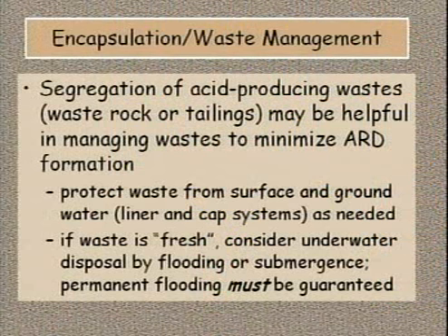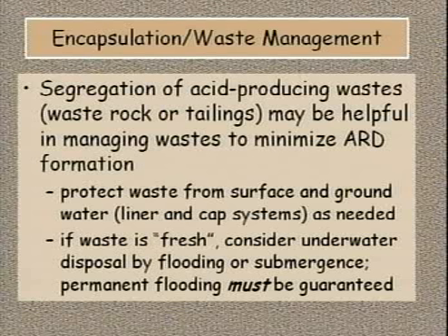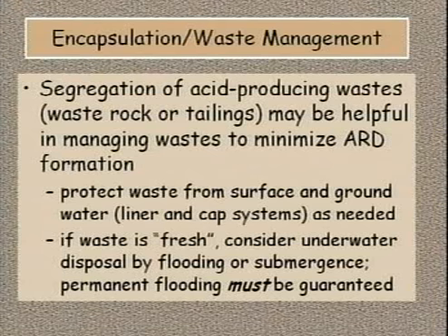Here's where all the prediction and characterization work that we talked about earlier really comes to bear. Mining typically involves the generation or excavation and movement of large volumes of waste. Unfortunately, it's pretty easy for these wastes to mix in this situation. However, with a little bit of planning, really problematic wastes can be segregated from the benign wastes so that encapsulation cost and effort can be minimized.